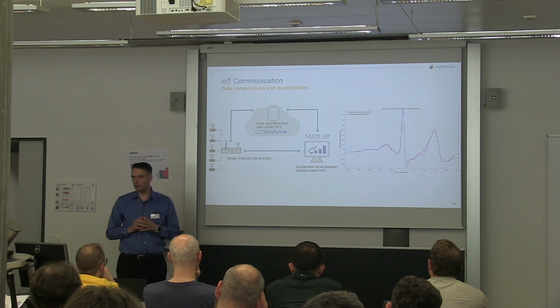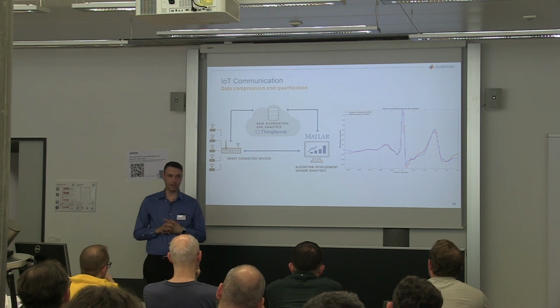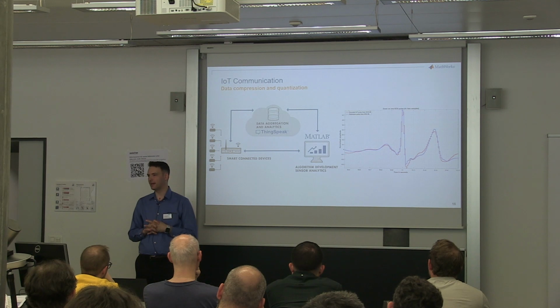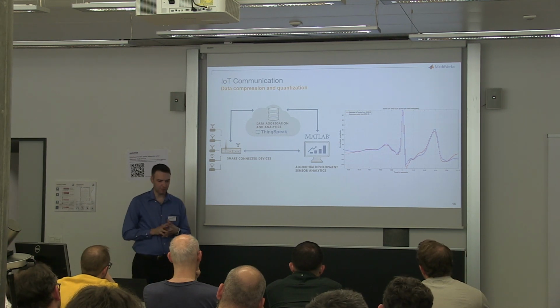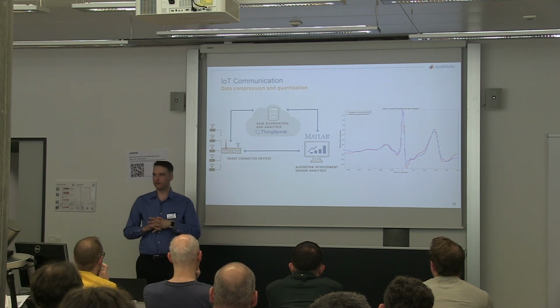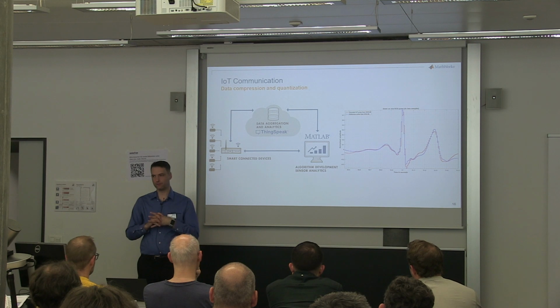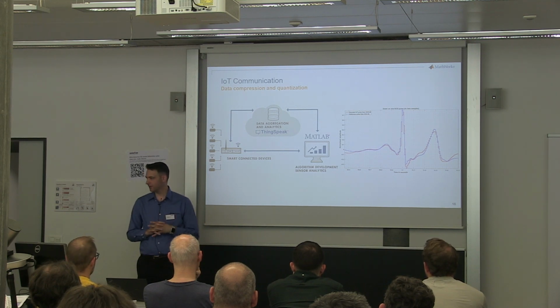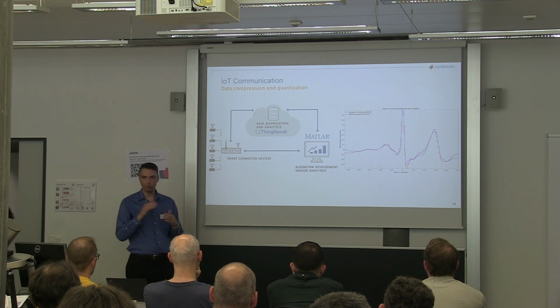Sending the data to the cloud has a cost, in the sense that you cannot send as much data as you want. You have to compress the data, okay? And in our case, the application is running at 510 Hertz. I cannot send 510 data samples of 64-bit precision, double floating point, every second to the server, so I will compress the data.